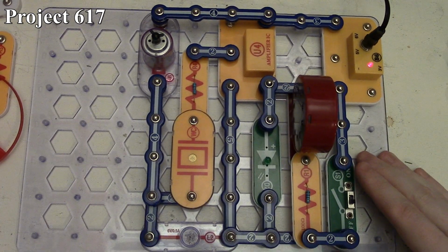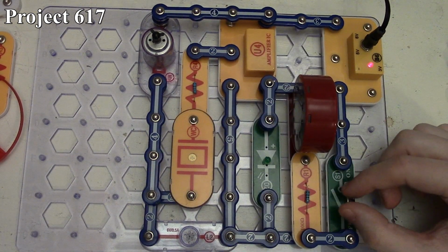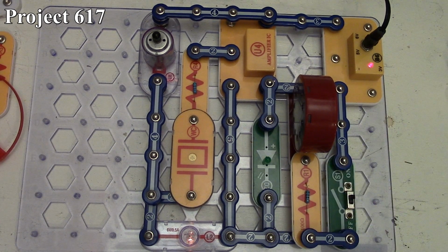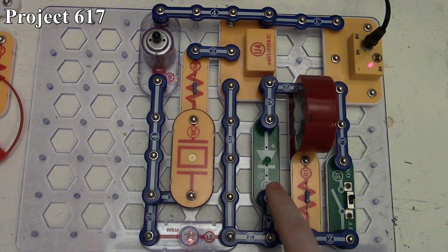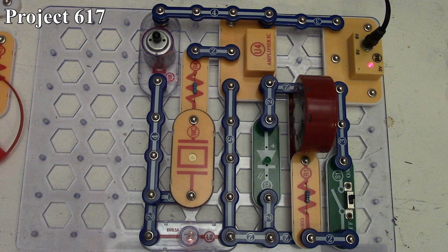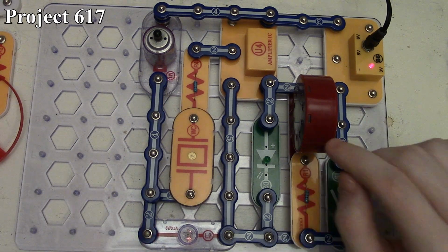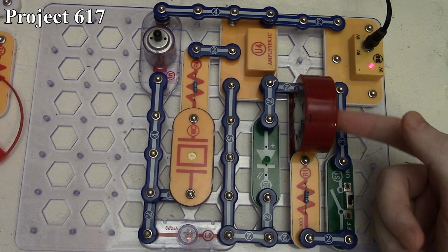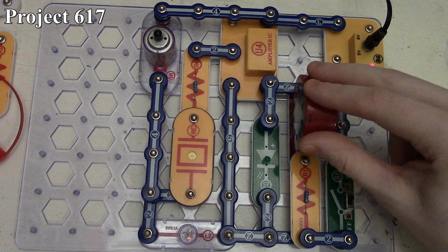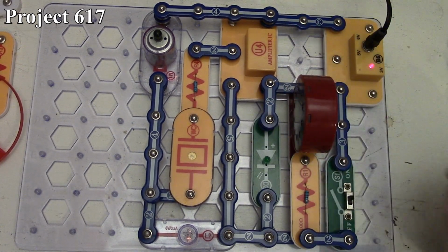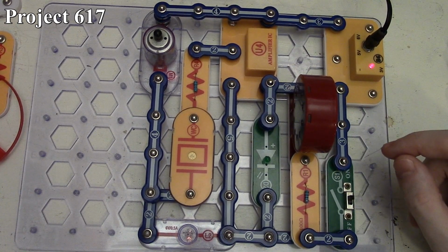So when we have the circuit powered up with the fan off the motor, our green LED lights up briefly there as the motor starts up, and it starts spinning. Our 6-volt lamp is dim because of the high back EMF on the motor there, and we can hear that coming through our speaker there from the output of our amplifier IC.